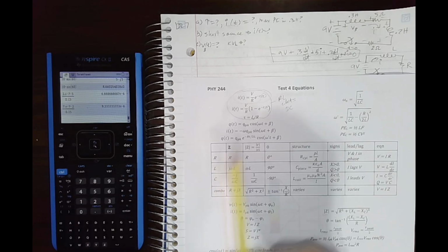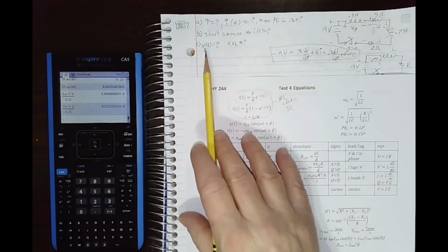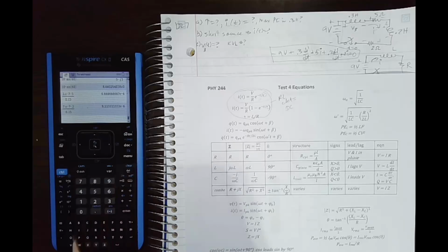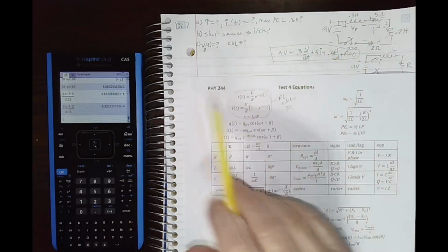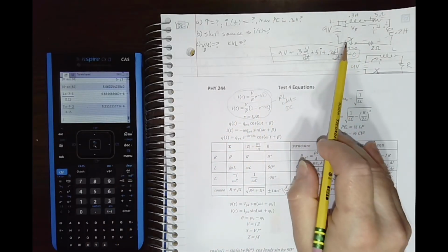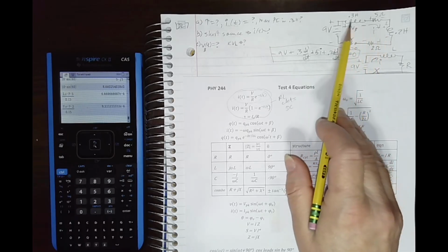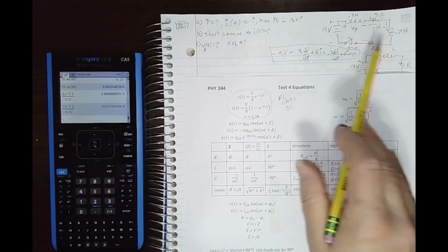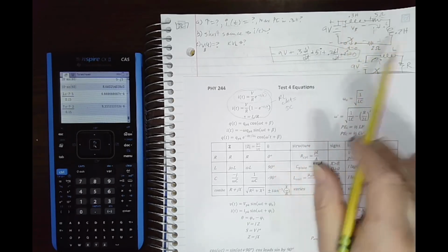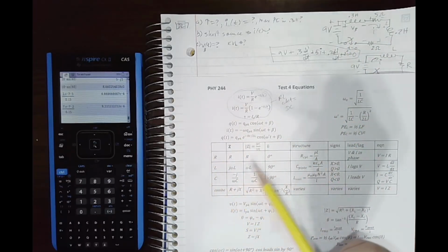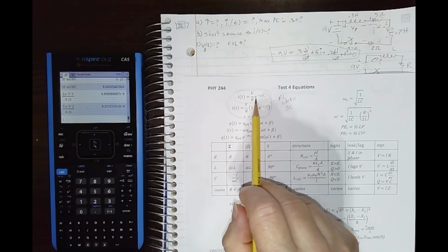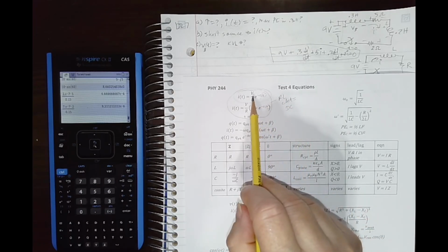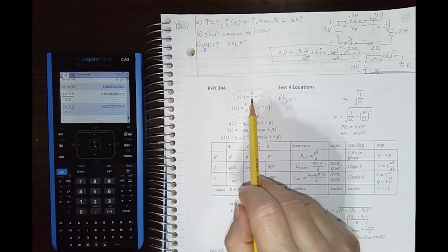The opposite happens if, say, the switch has been closed for a long time, and down here we short out the source. We take the source out and just close across here so that all the current goes through here and the source isn't in the circuit anymore. We could think of opening the switch on the circuit if that helps, but basically shorting across here will take the source out of the circuit. Then the inductors, again, don't like the change, and so they will try to hold the current up until they get rid of all the energy that they have stored in them, and then the current goes down. So this first one, an exponential with a negative in it, starts high and goes low. So this must be when the switch has been closed for a long time, and then the source goes away.